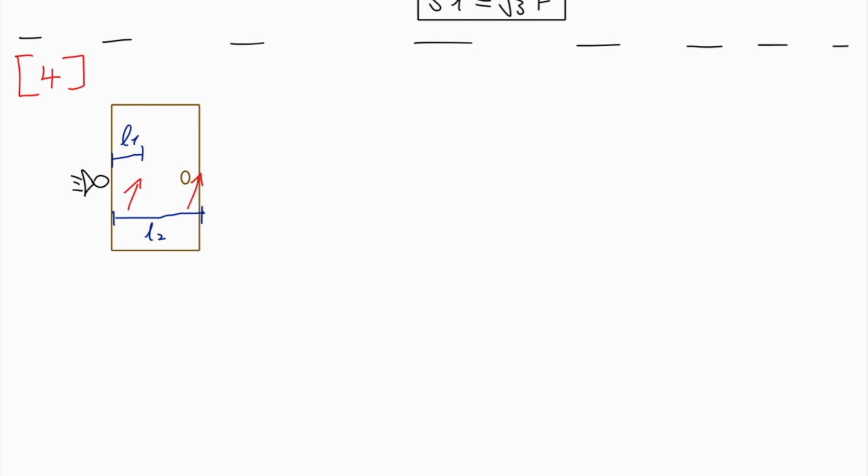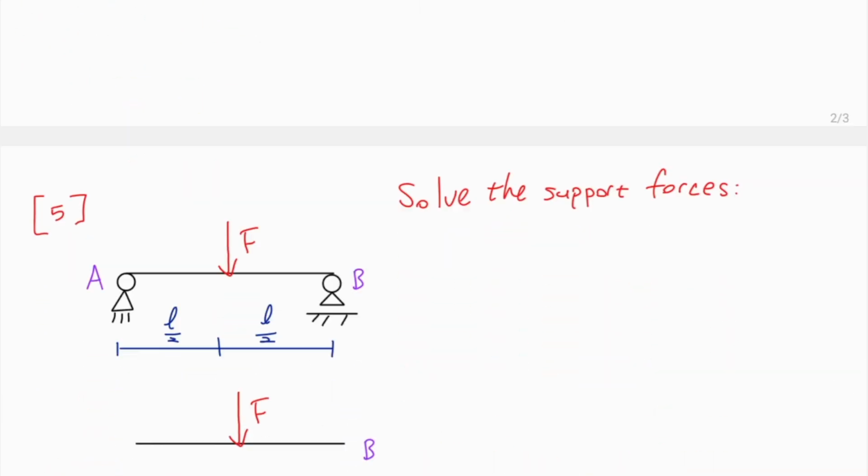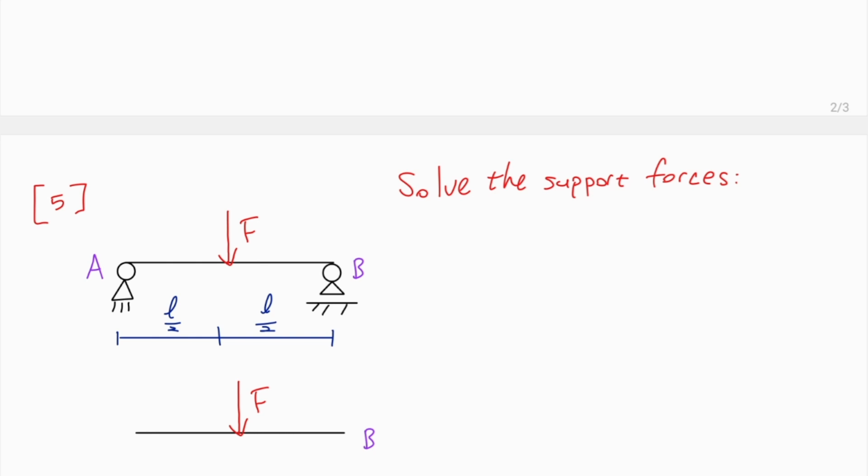And it's very important to note that moments are actually induced when a force travels a perpendicular distance to a point. So a force that does not travel perpendicular to your hinge will never generate a moment. So for example, if you try to push a door in this direction, you will never be able to open it, okay? This does not induce a moment. So a very common exam trick that you might encounter is where you're supposed to take moments such that you only have one force in your question, and therefore you can solve for this unknown force, okay?